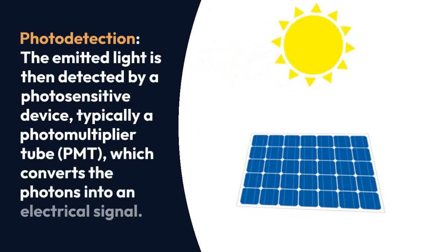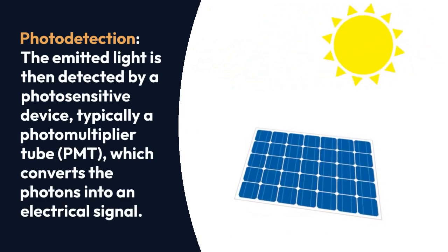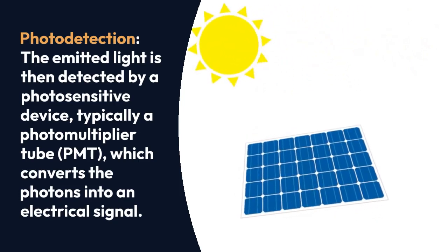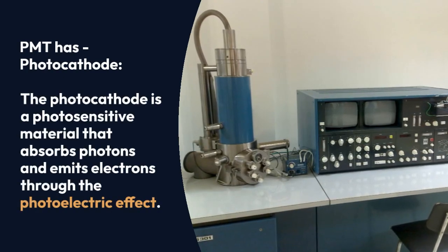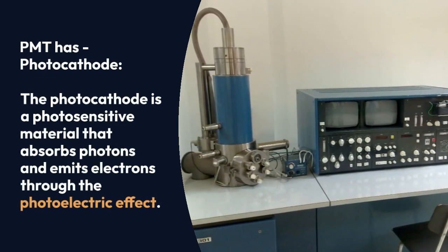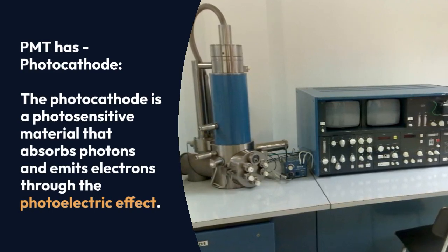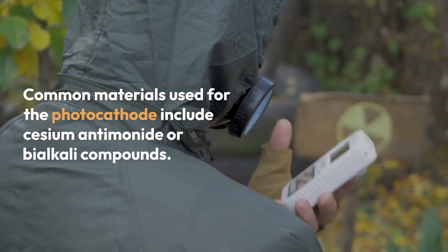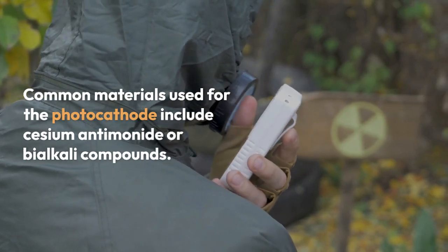Photo detection: the emitted light is then detected by a photosensitive device, typically a photomultiplier tube, which converts the photons into an electrical signal. The PMT has a photocathode. The photocathode is a photosensitive material that absorbs photons and emits electrons through the photoelectric effect. Common materials used for the photocathode include cesium antimonide or bialkali compounds.